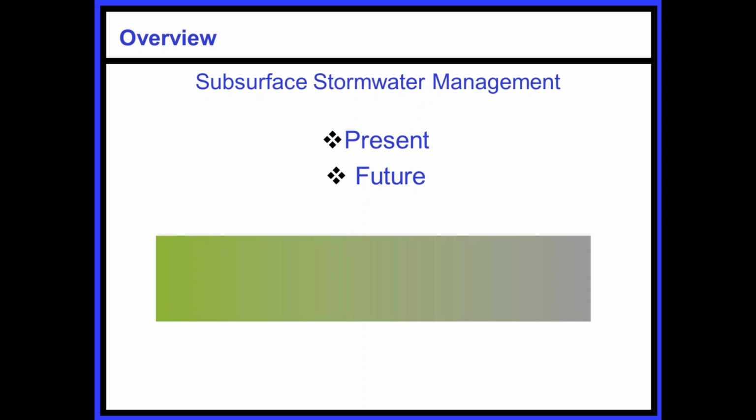Just as a quick definition, gray infrastructure as we know it today is typically what you would think of for a stormwater system: an inlet structure and piping, flared-end sections, could even be channelized ditches, etc. That's gray. Green is grass, plants, flowers, trees, as well as other methods to mimic a pre-developed condition, so that the idea is for the water not to leave the site. It stays on the site and then has an opportunity to infiltrate down into the ground.